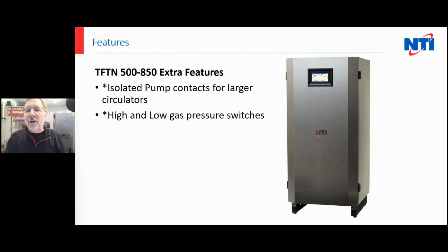Anyway, high and low gas pressure switches. Please put regulators in that regulate. Most of these jobs go in places where you have high pressure gas coming in so they can reduce the size of the line. So instead of having 4-inch gas mains, they can run 1.5 inches at 22 PSI and then reduce it. Know what your gas pressure is coming in and get the correct reducer.